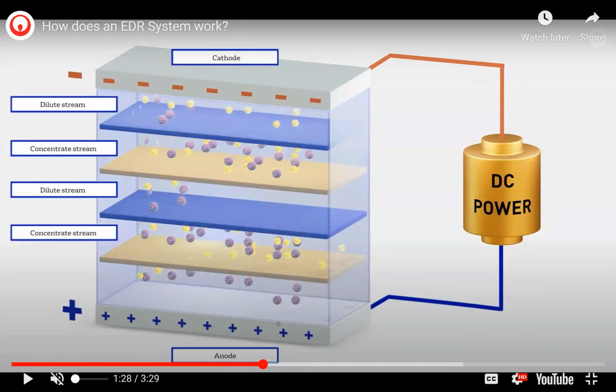So in the alternate chambers, there is the anion exchange membrane and the cation exchange membrane, as you can see in the figure. If the anion exchange membrane is here, it is passing Cl minus, and it is reaching this chamber. And this brown colored surface is the cation exchange surface, so it will pass Na plus.